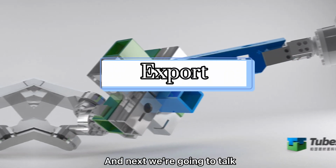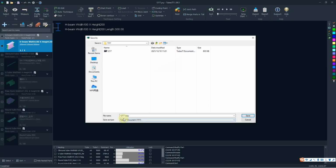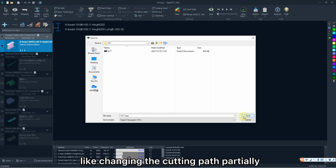And next we are going to talk about export. Click this icon on the left top of the interface. TubesT will export a file in YXY format, which is not used for cutting software, but is an engineering file for nesting. It will save all the results nested, parts imported, and the processes added. If you want to modify it lightly, like changing the cutting path partially, just open this file, which is able to save much redundant operation. Then you're allowed to continue the editing saved at a later time.